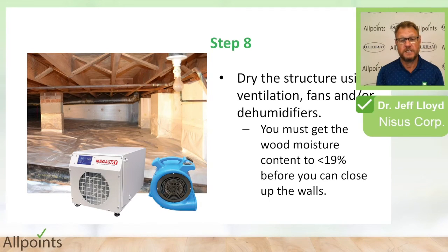If you've got access to dehumidification, commercial dehumidifiers, for example, combined with fans, that's wonderful. And typically you want to set your dehumidifier to 50% relative humidity. If you set it drier than that, it won't make it dry faster, but it will over dry. And typically the safe relative humidity, the healthy relative humidity in a home, is between 40 and 60% relative humidity. And if you take the home down to 50% relative humidity, that will allow the continued drying, and you've got your fans running hopefully, so you're moving the air around as part of that